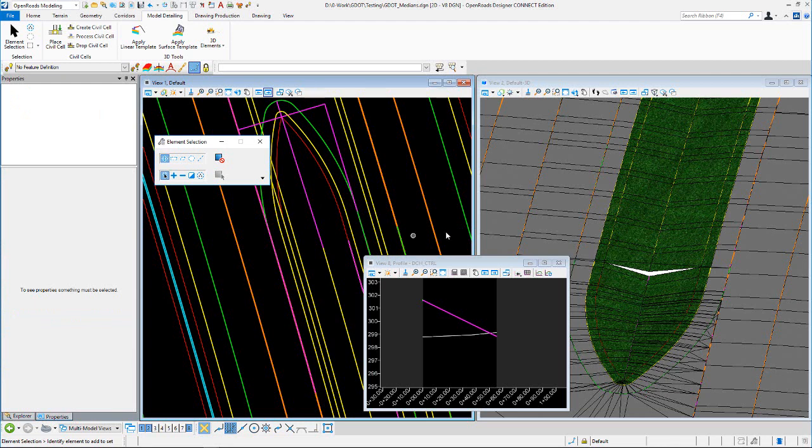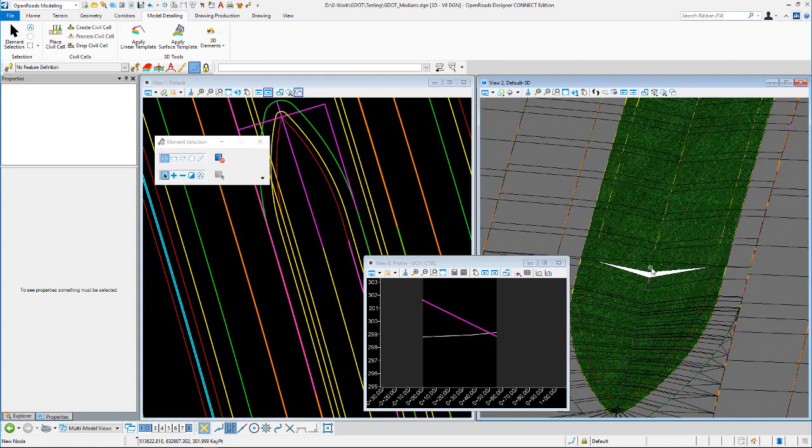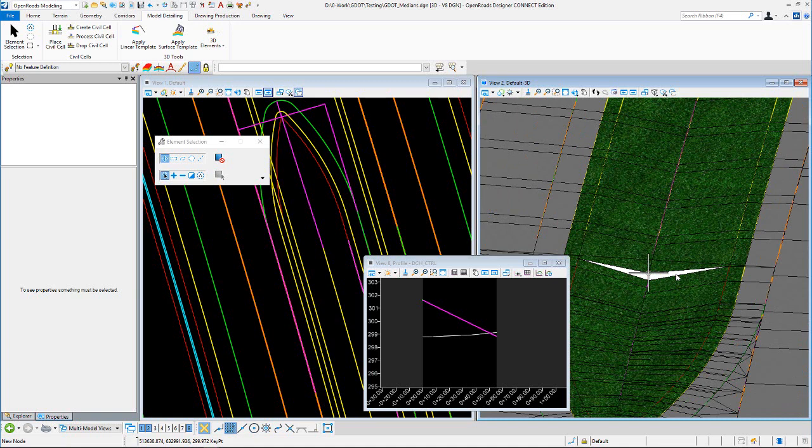Okay, and then I've got to just line this up vertically. I've looked at profile intersection point a couple different ways to do this, and I think because of the way it's touching right there on the edge, I'm not seeing it. So those other methods, I'm not able to do it. So basically I'm just going to come in and do a snap to that ditch line right here, so I can see that 299.972 is the elevation I need to get to.